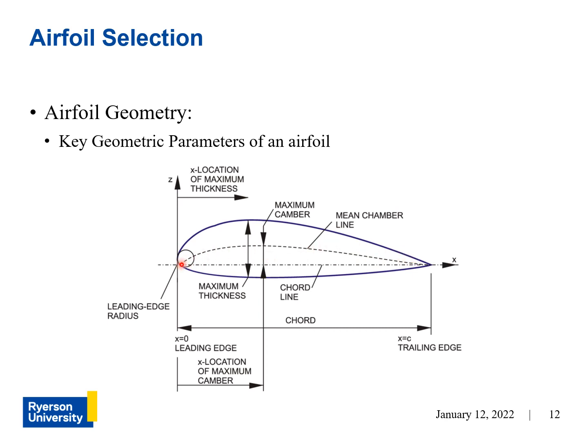So if you were to find the distance between the upper and lower surface such that the line is perpendicular to this mean camber line, that will be your thickness at that particular point. Now, again, the thickness of the airfoil is defined by the maximum thickness. So if you go along this line, you'll find that the maximum thickness occurs here, and that is the number that you use to define the thickness of the airfoil.